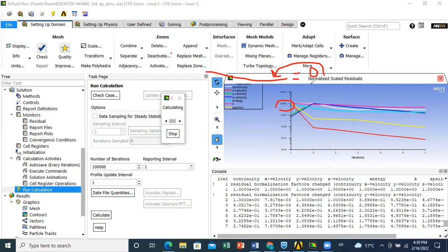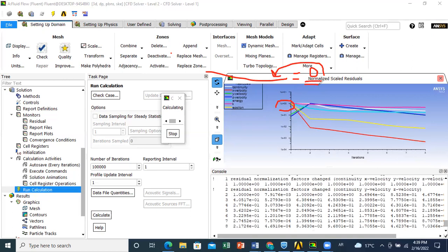This should be equal to 0. Now, when you do the calculations, the simulation, you will not exactly reach 0. If you reach 0, this means that you reached the accurate solution. The closer this number is to 0, the closer you are to the real solution. So what I mean by residual is the number you obtain here.